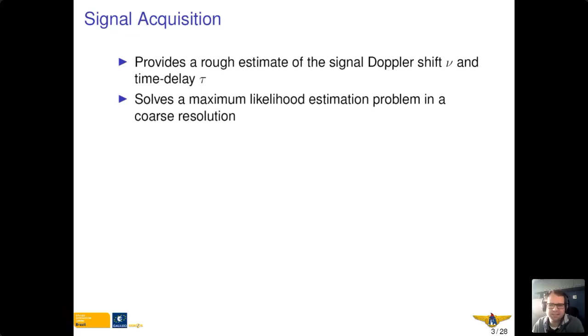We discussed this yesterday: with the autocorrelation function of the signal, we have to hit the peak, the global optimum. We need to hit, in our case, the concave region around the global optimum. If we don't, we can end up tracking a side peak. It's not bad, we can still follow the signal, but we will have a large bias in the range.